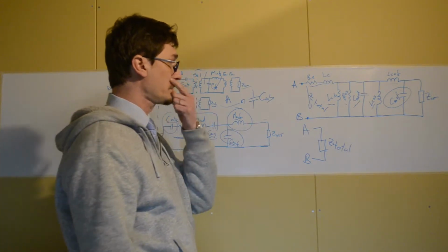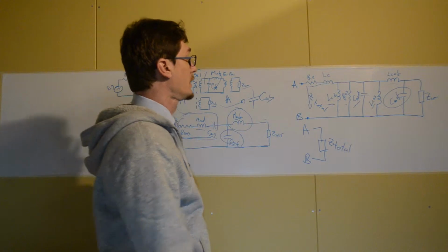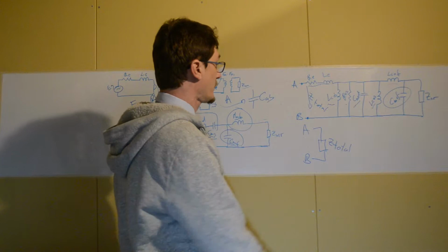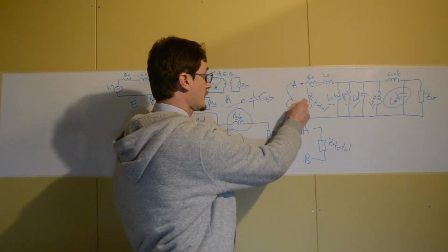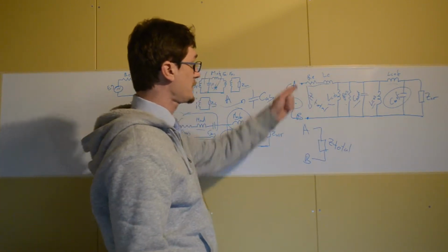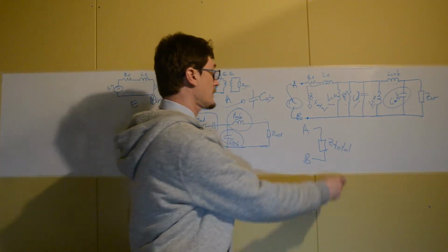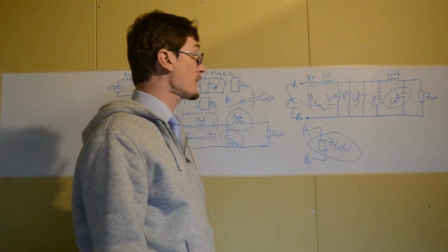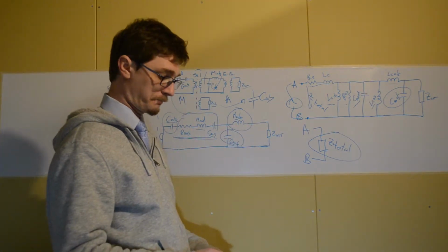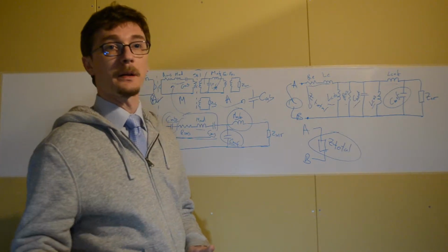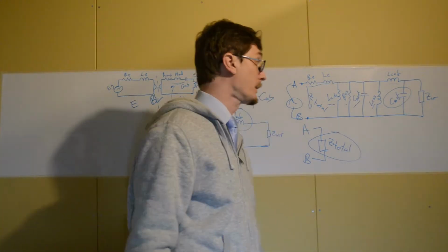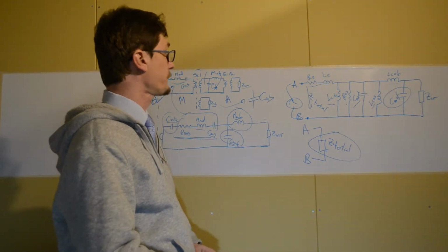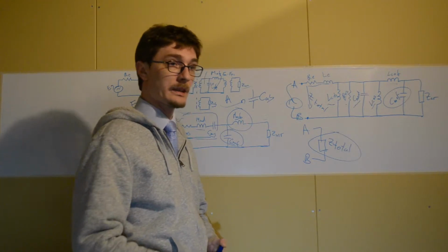So now all we have to do is just apply circuit theory to calculate the equivalent total impedance of the circuit. So we will have a generator here, right? Basically between point A and point B, what we want to do is represent it as a total impedance. We can do this very simply with LTSpice, for example. It's free software. You can put in this circuit and calculate the impedance, plot the impedance, or you can use Scilab, which I like.